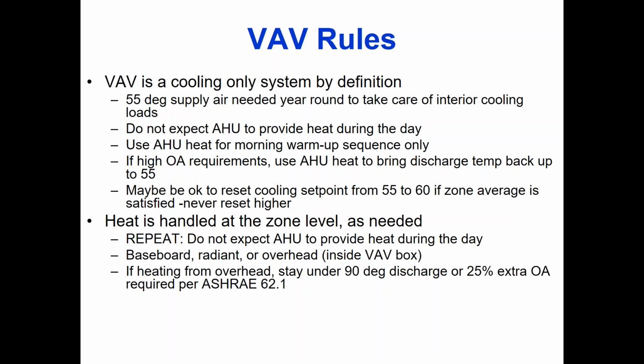I said on my slide here 90 degrees, figuring maybe you might heat the space to 75, which is kind of hot. But if you heated the space to 75, the hottest supply temperature you could have would be 90 degrees.